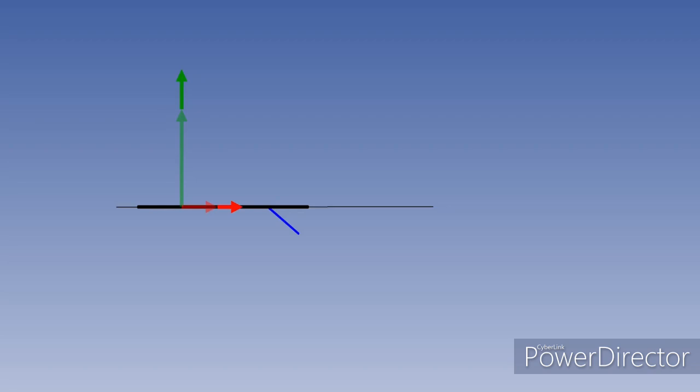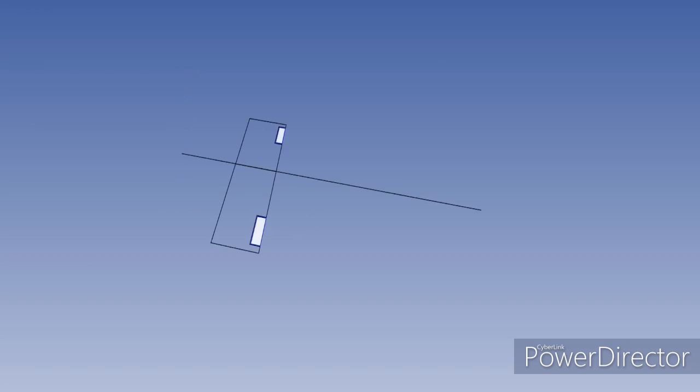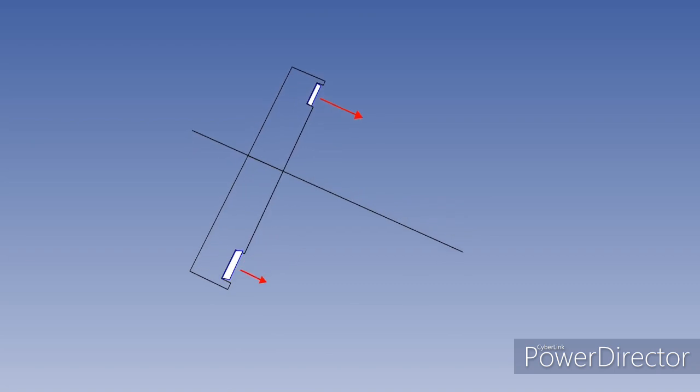Only the downgoing aileron is illustrated. The adverse aileron yaw illustrated here is greatly exaggerated for clarity. The result of adverse aileron yaw is a yawing moment in the opposite direction to that required. If you roll the aircraft, in this case to the left, a yawing moment to the right is generated. This is both aerodynamically inefficient and physically uncomfortable for all on board. It must be pointed out, it's only during the roll, while the ailerons are displaced from neutral, that adverse aileron yaw occurs.